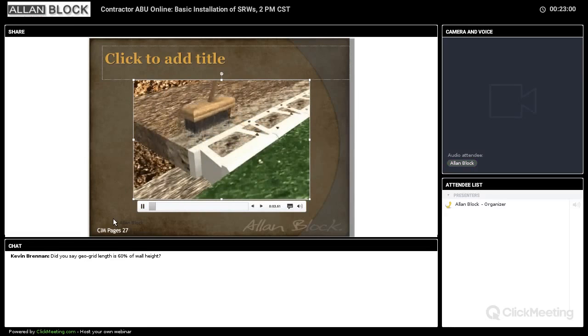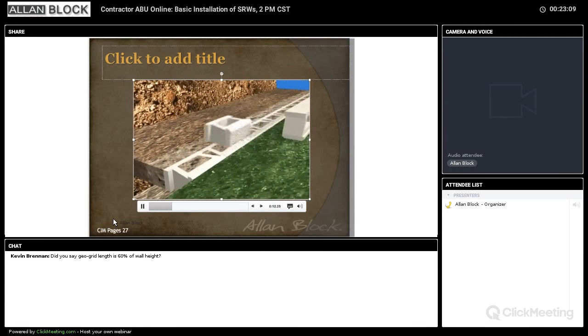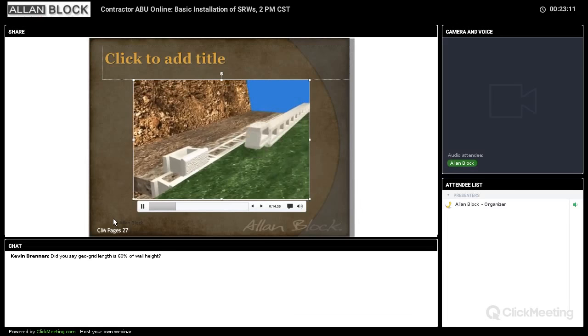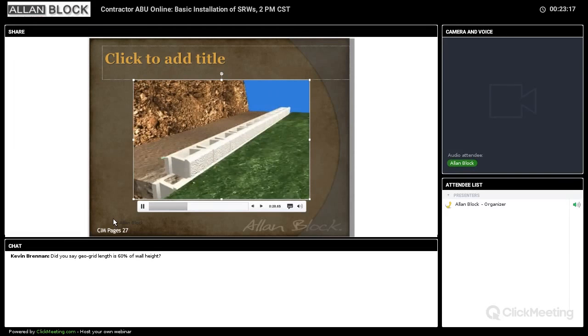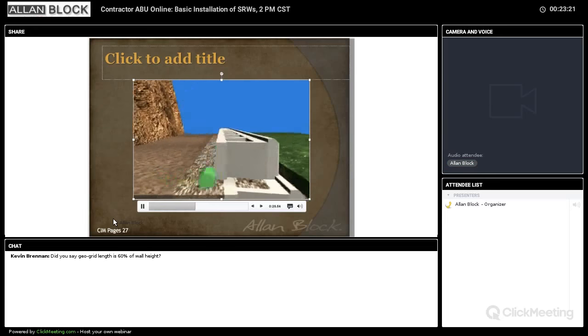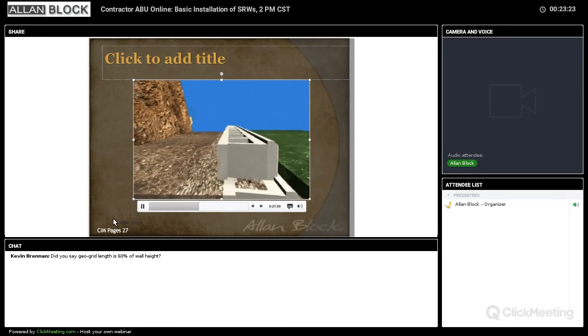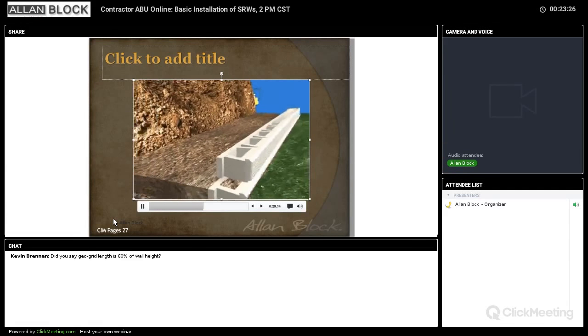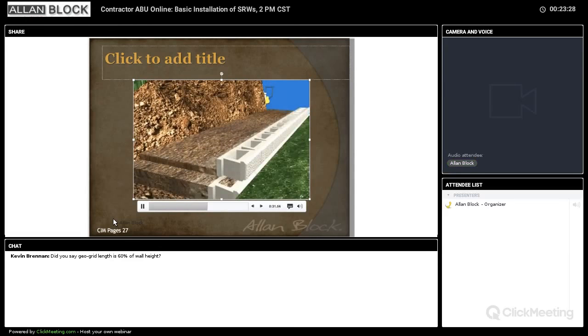After we've placed the first course and we're going to place the second course, we want to make sure it's all cleaned off so the pebbles don't cause any problems. And notice when the blocks go on, they slide them to the side. They place them and slide them, place them and slide them. A little bit of slide actually takes the slag off of the top of the block, if there is any, and it makes the top of the block a little smoother. So we encourage you to drop it and slide it, drop it and slide it.